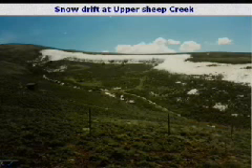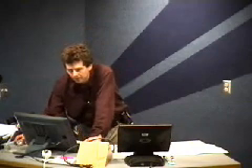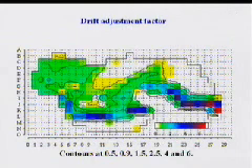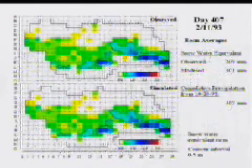So on 6 or 7 occasions through each winter, they would construct a map of the distribution of snow from manual measurement. So we were able to use those to estimate this drift adjustment factor that calculates the amount that you multiply the precipitation input by to say how much snow accumulates at each point. And then that's used as input to the model.